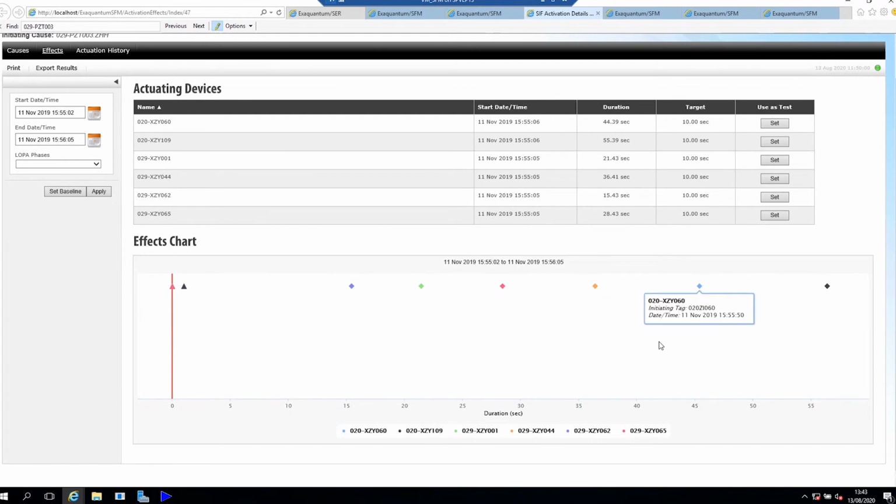Okay. In this particular example, like I said, we are monitoring not only the primary elements, but also the secondary elements in terms of the valve travel times. All right, so it is giving me valve travel times in this view. All of them are well past the design target. The reason for it is that I was manipulating the valve manually, and it took me time to go through every one of them.